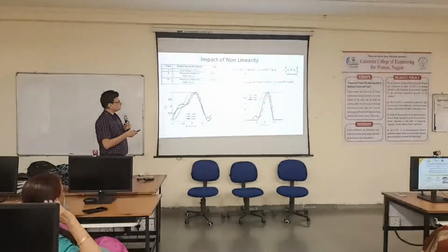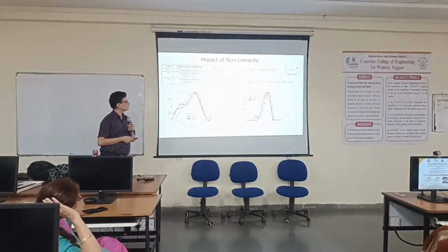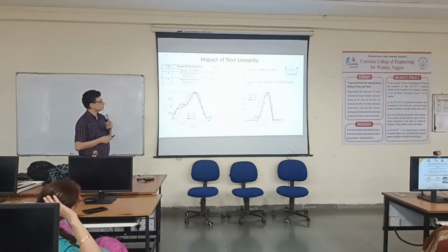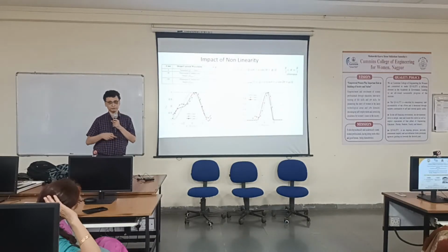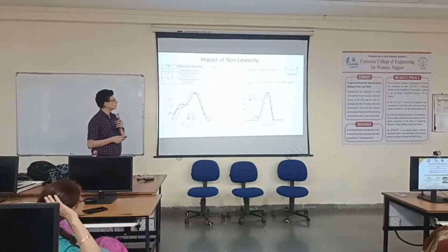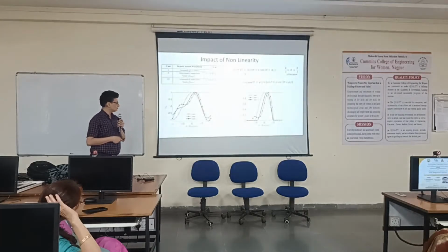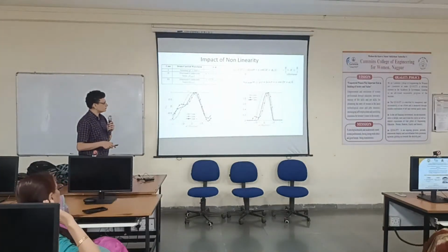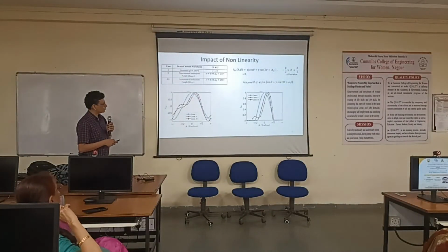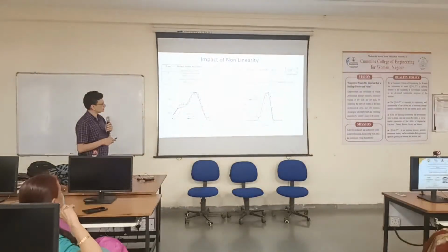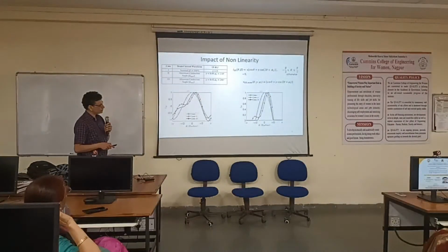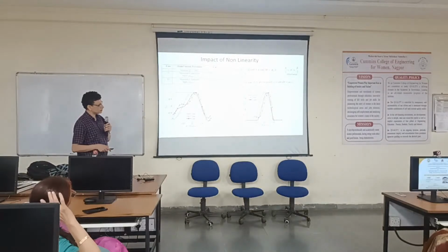So we chose three different cases. One is when our conduction angle is 180 degrees, that is when the amplifier is a pure class B amplifier. The next are the maximum conduction angle and minimum conduction angle. Here we see the voltage and current waveforms for the three cases. This blue line is the waveform for case 1, when it is class B, and as you can see, this blue line has a 180 degree conduction angle.